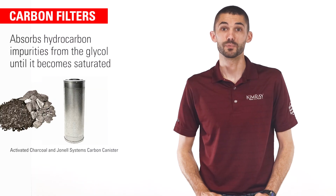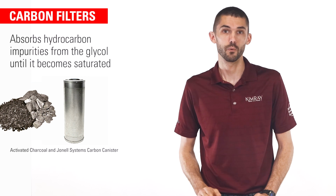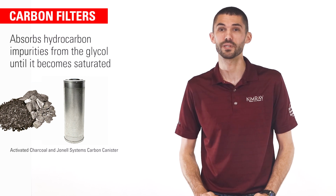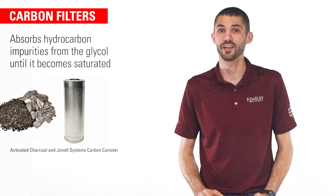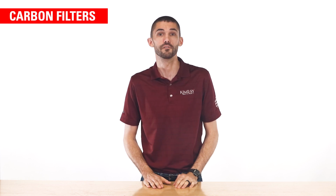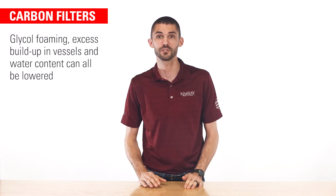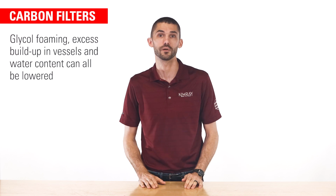The carbon filter absorbs hydrocarbon impurities from the glycol until it becomes saturated, at which point the filter needs to be replaced because it cannot absorb any more and the hydrocarbons will pass through it. There are many different contaminant sizes in a typical dehydration system, and if the pore size of the carbon is too small, larger contaminants can clog them and decrease the effectiveness of the filter. With these carbon filters collecting impurities, glycol foaming, excess buildup in vessels, and water content can all be lowered.